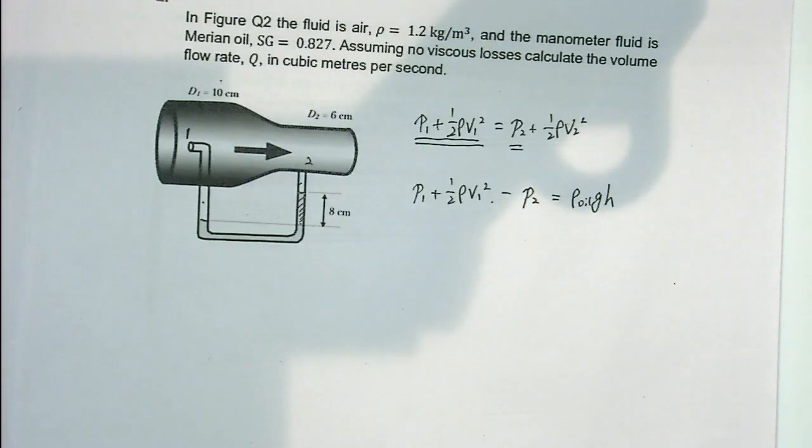And then we know the diameters of the nozzle. So the second one we could link is applying the continuity equation as well. We suppose that because the flow is very slow for the air, we assume that it is the incompressible flow.